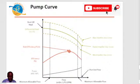While your head will be represented, you see, on the vertical axis. In this case, that is differential head, which can be expressed in meter or in feet. All right, your flow can be expressed in cubic meter per hour or liter per second or what? Or gallon per minute.